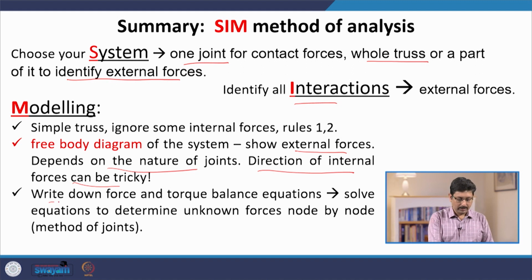Then the final step is to write down the force and torque balance equations and solve them to get the unknown forces. Usually in the case of a truss problem, we go node by node and solve for the unknown forces node by node.